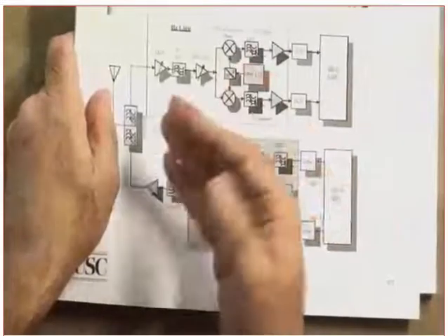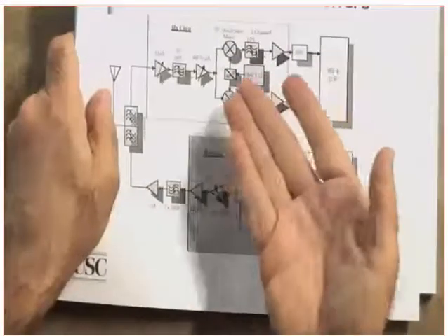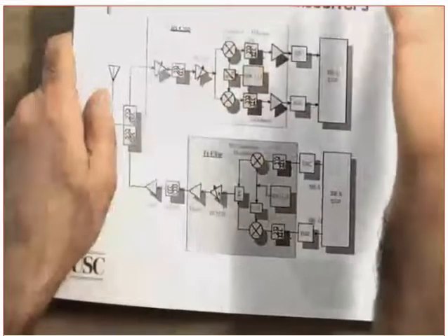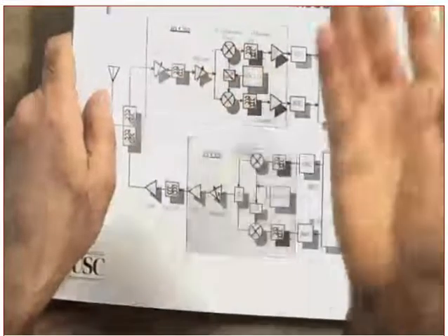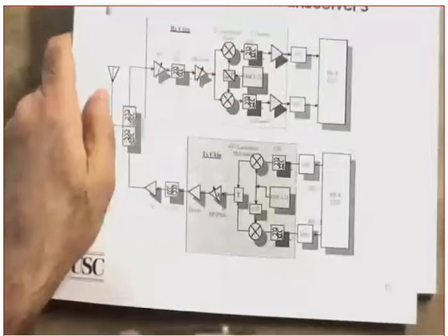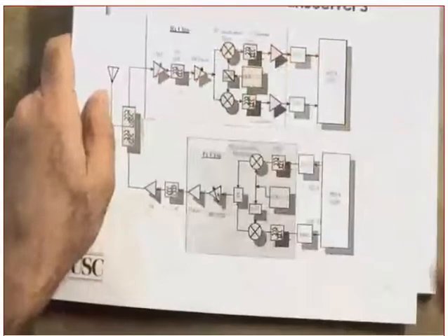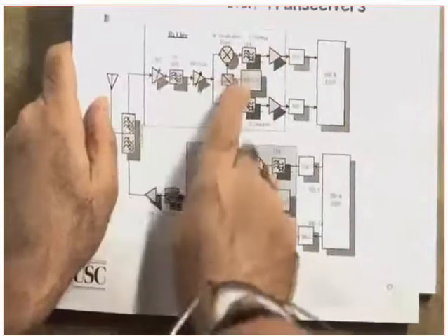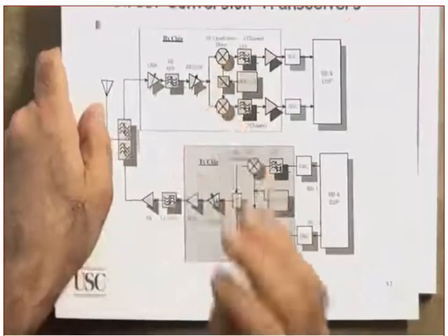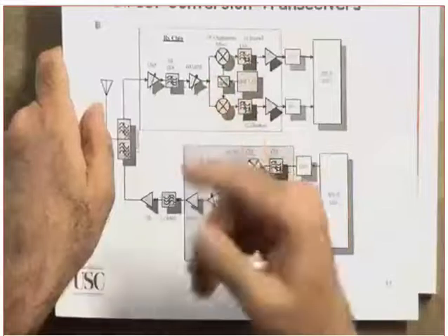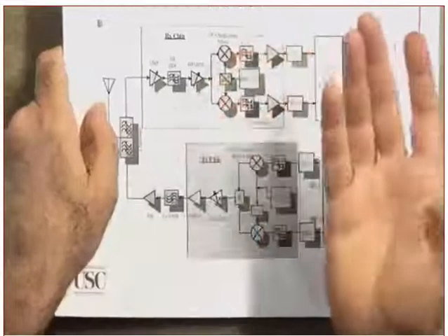When you do IQ at very high frequency, by the way, what are we talking about? What frequencies? For example, if you are using 802.11, we are talking about frequencies in the range of 2.4 gigahertz or 5 gigahertz and so on. Clear? These are not low frequency components. Designing the IQ, you need to be very precise in making sure that the I channel and the Q channel are balanced. Are you following me or not?